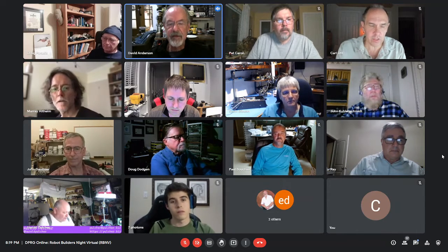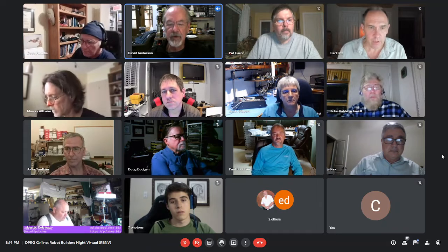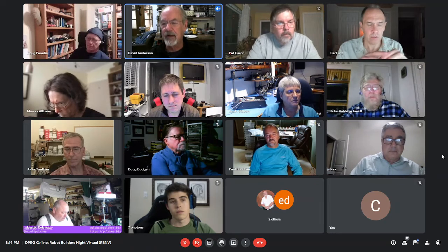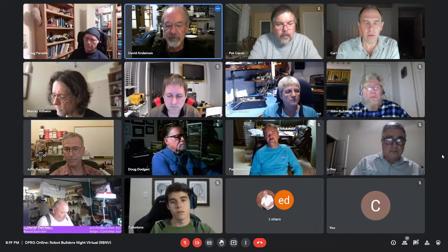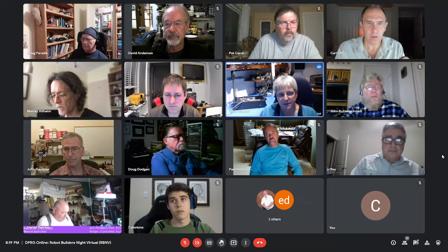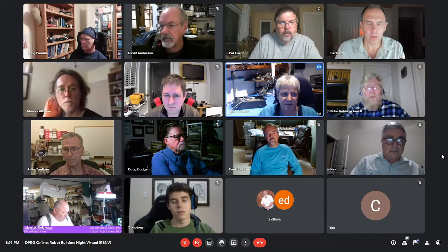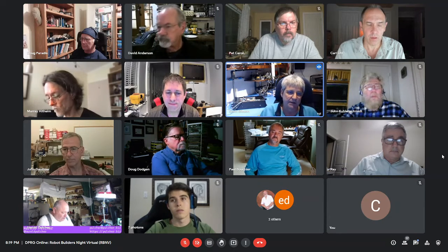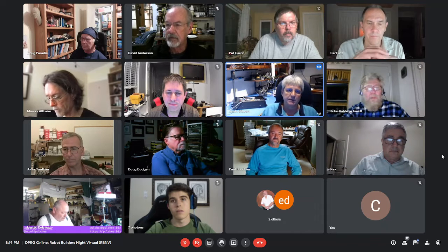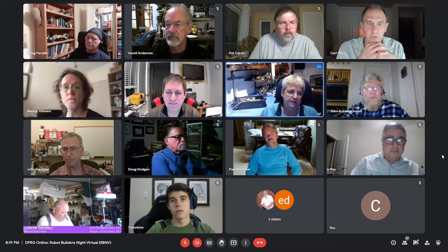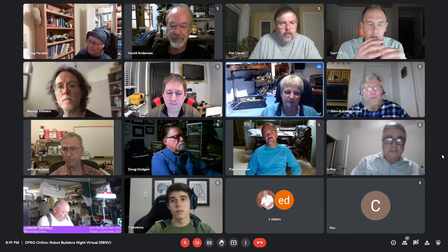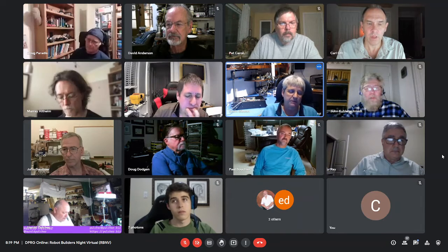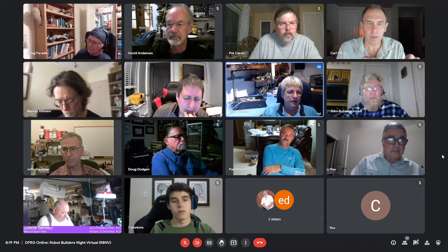I think the Feather board is also programmed that way, Chris. There, you hit the reset button twice and it puts it in a download mode from their own bootloader. But I think the ST family has boot mode pins. So it's a matter of what the pins are set to when the power comes up and where it looks, because I think you can actually bootload into it over serial or USB. I think there's a number of options, but you're right, Chris. You have to have low level access, like a JTAG or control the boot-up pins on that part.